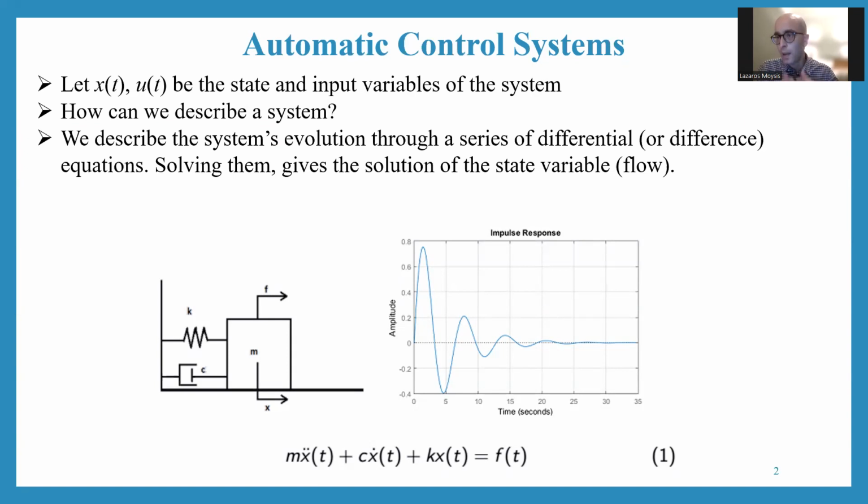Usually, the most fundamental approach for modeling a phenomenon is through a set of differential equations. You may have one differential equation, or you may have more, right? And these differential equations describe the relation between the input, here this function f, which is the force that we give to the system, and a state variable of the system. In this case, it is the displacement of the body. And of course, the differential equation includes the force, the displacement of the body, the velocity, which is x dot, and the acceleration, which is the twice differentiation of the displacement, right?